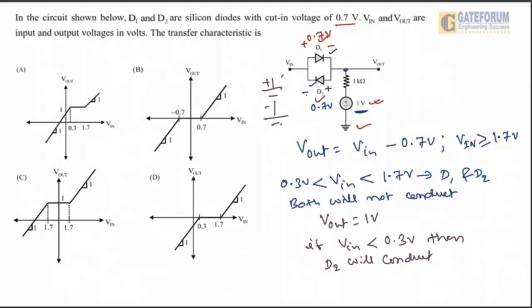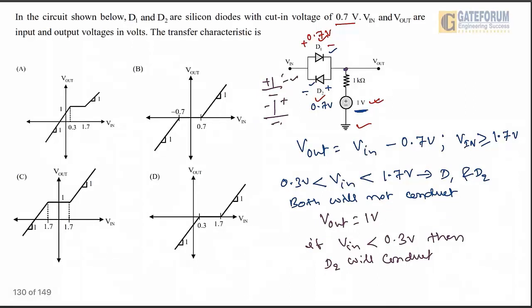Whenever it changes polarity to minus here and plus here, then the second node is minus, and that voltage whatever appears here, plus 0.7, will become the output voltage for the negative. It means from 0 negative onwards.